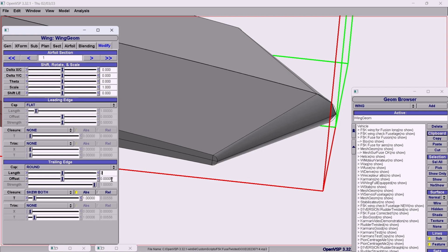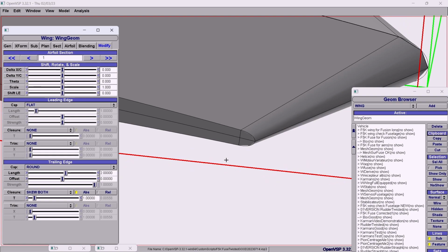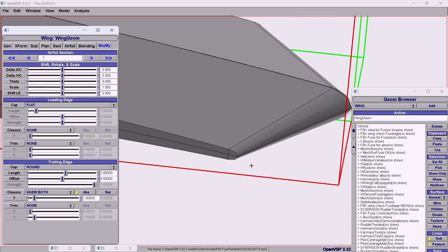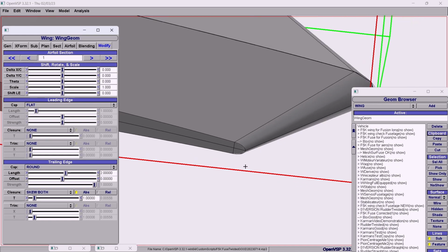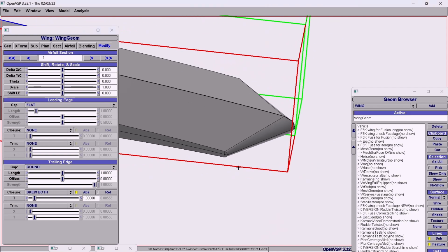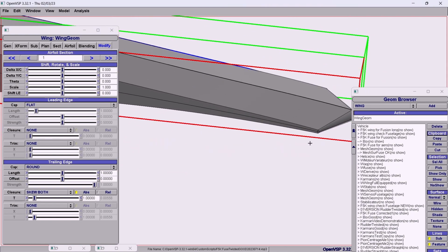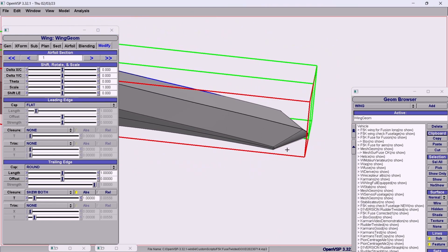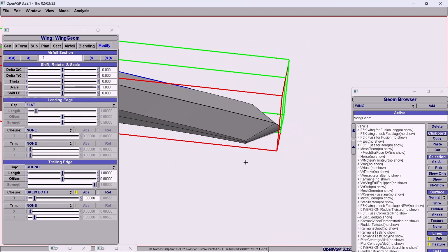And I can increase the length of the edge, but it makes no sense also because during the milling, this type of curvature with a bit of 1 millimeters, it's not going to happen. So let's come back to 1 millimeters. So I will have a slight difference in length in the code of 0.5 millimeters, but that is nothing.